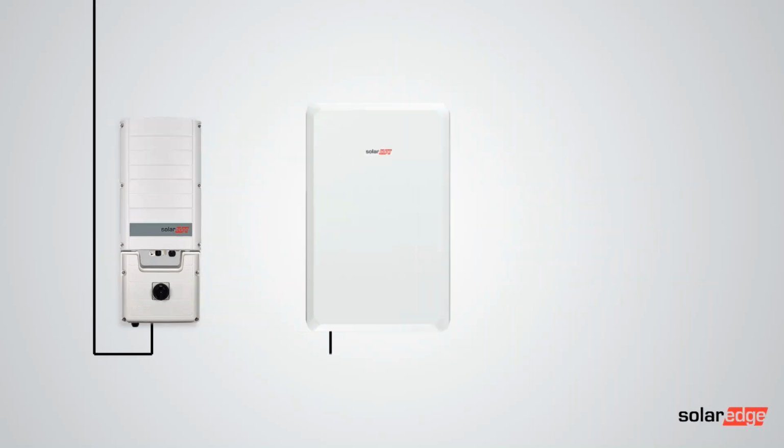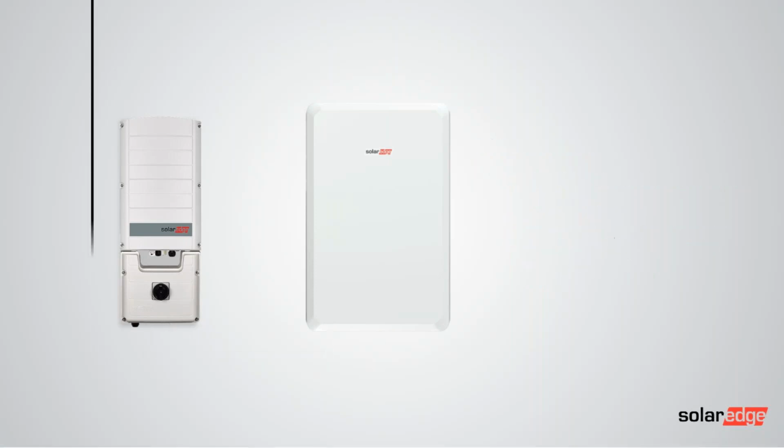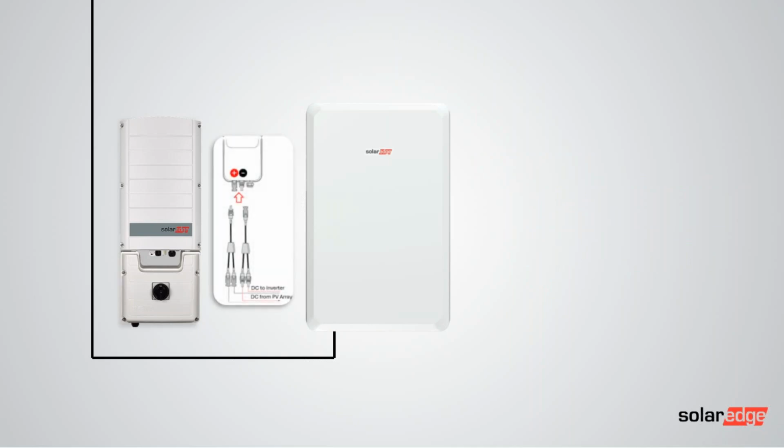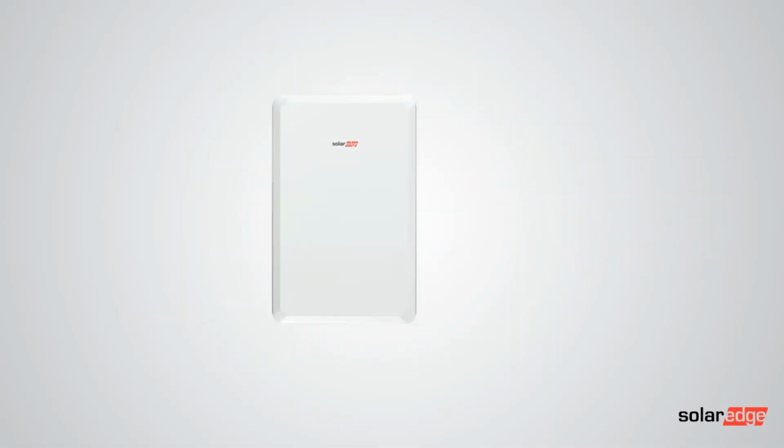Now, there's a couple of different options on how you can do the wiring, really around the fact that this could be an add-on or a battery being added to an existing installation. If so, then you've already got the DC coming down from the roof to the inverter. So you'll need to join the DC to that DC because the three-phase Resi inverter's only got a single DC input. So you need to bring them two together in the DCD. Alternatively, if it's a new install, you can bring the DC straight to the battery and then use one of our branch connectors and then use the single input into the battery. A nicer, simpler way to do it. I mean, you could do this with an existing install if the DC cable allows.